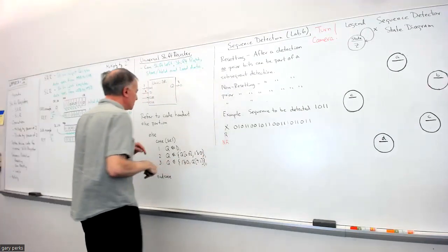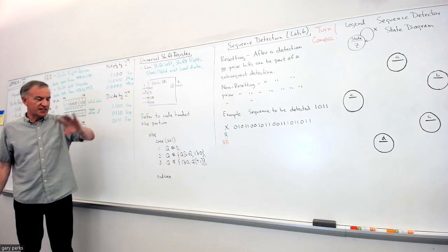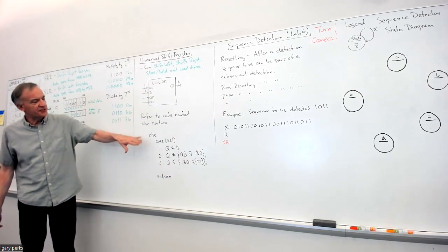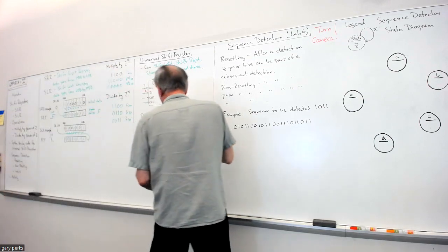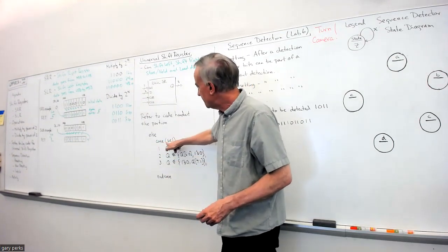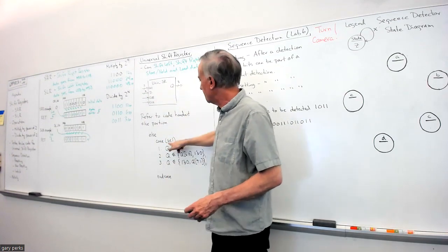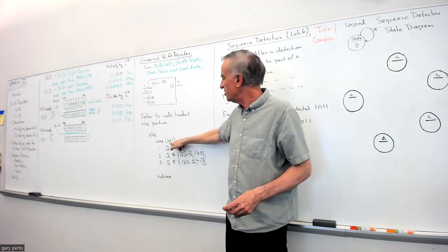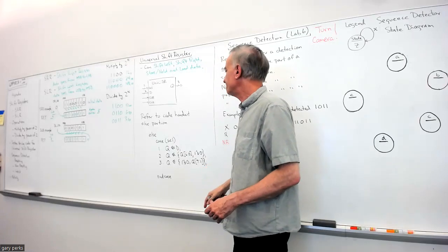But what I wanted to focus on in this discussion is in that code, under the else for the if, there's a case statement. So we have this case statement within the if, under the else, and you can see that the case depends on input SEL, right? So remember, what goes inside these parentheses of the case statement? When that changes, that's when the case gets evaluated.